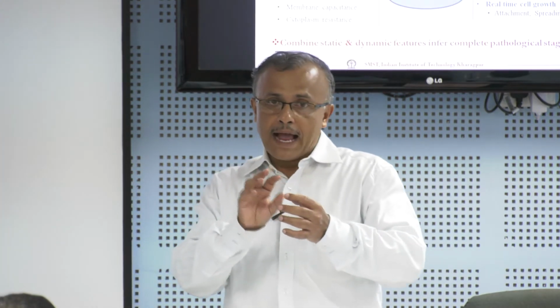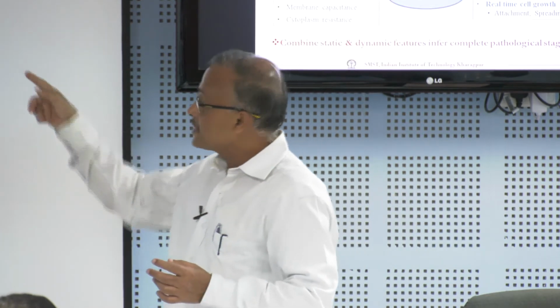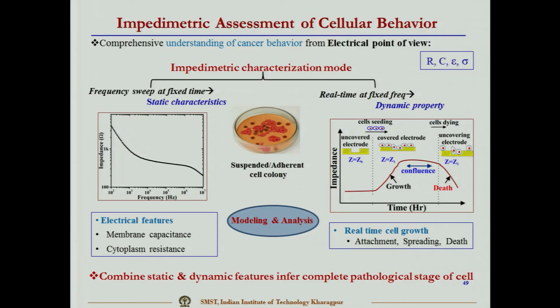Now, at a fixed time, if I sweep the frequency from low frequency to high frequency, then the characteristic impedance will change. That change will occur due to the change in the frequency, because the resistance will not change with the frequency, but the capacitance value depends on the frequency. So its value changes, and so the overall impedance will change.